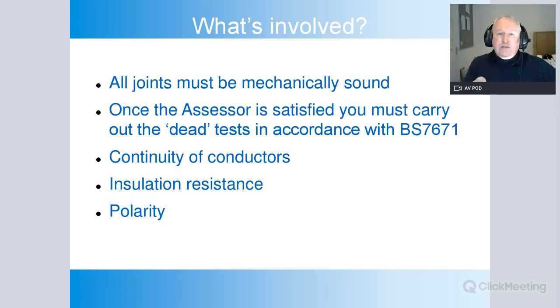Once your assessor has checked that all your equipment is secure and the wiring is up to standard, he then asks you to do some testing. A lot of people get really stressed and worried about testing, but you're just going to do what we call the dead tests: continuity of conductors, insulation resistance, and polarity.